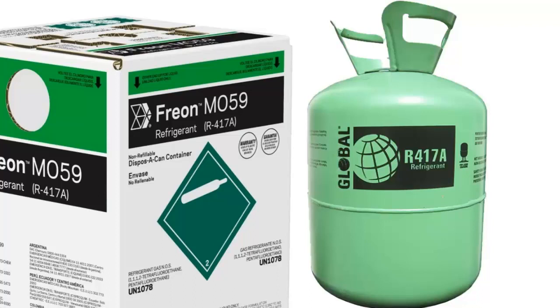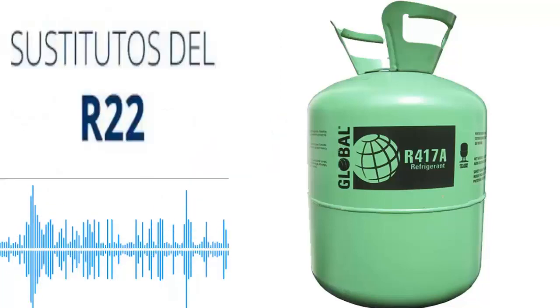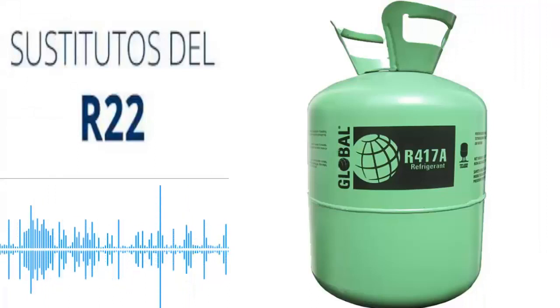Therefore, this refrigerant is usually used specifically for air conditioning applications when temperatures are greater than 0 degrees Celsius. However, as the R-417A is a substitute for the R-22, in some applications where the R-22 was present, R-22 was replaced by the R-417A to be able to achieve that the equipment works for a few more years. It can be found in applications of medium refrigeration. That is why we talk about temperatures of 0, -6, and -10.